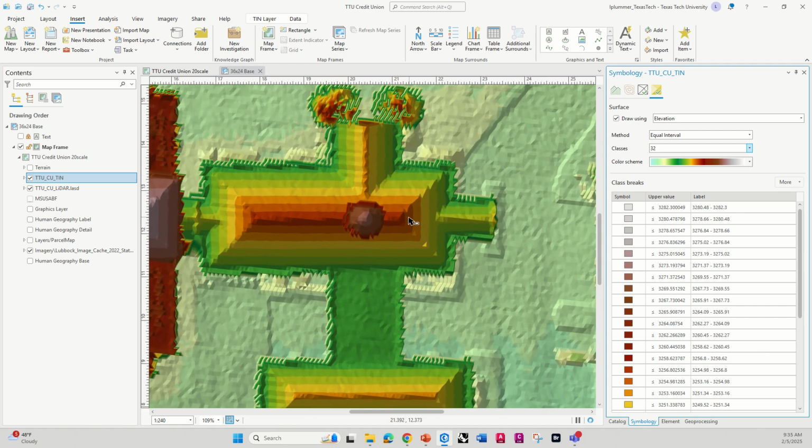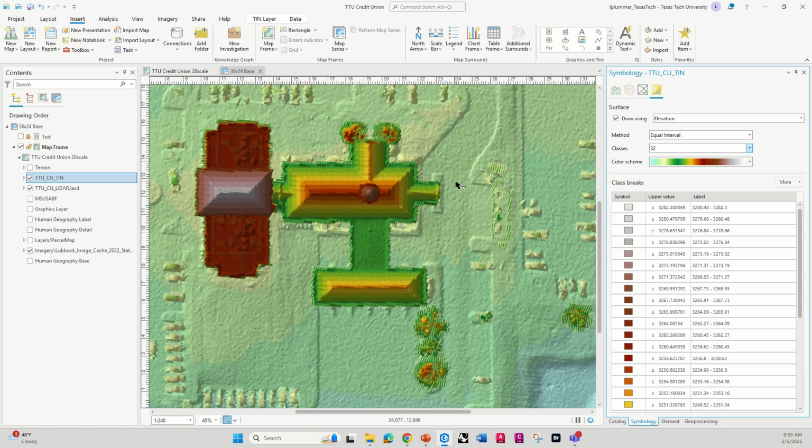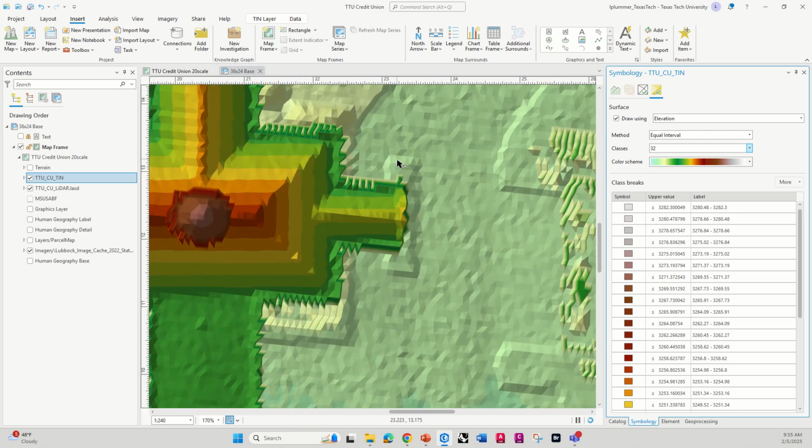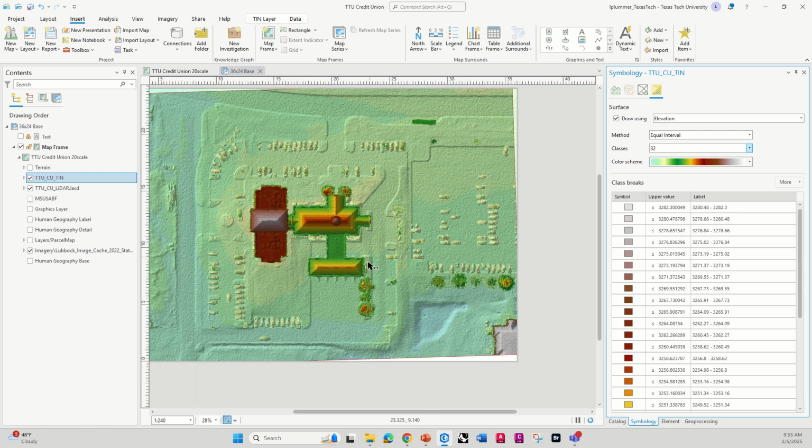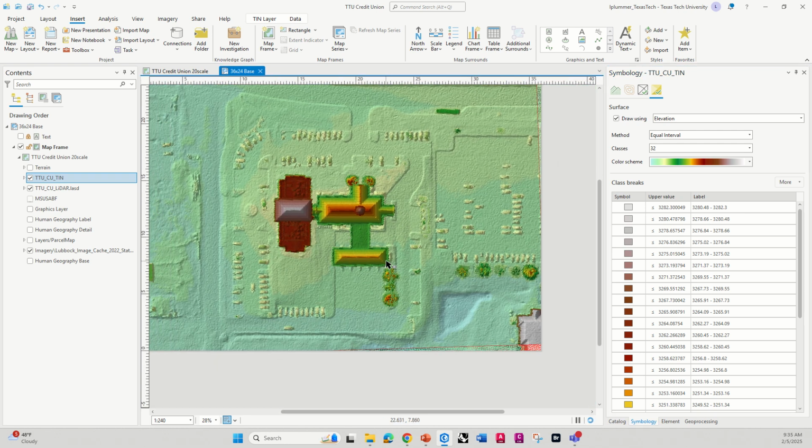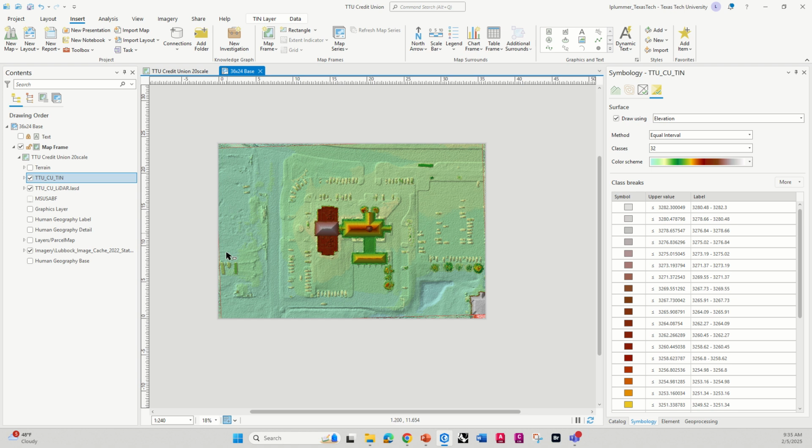Will was showing me, you can even see the height of the roof as it descends down. Okay, you can see that garden bed around the drive-through, and you can see, most importantly, the general lay of the land as to how the civil engineers graded it. And you can see that nearly all the water is coming down, not all of it, but at least on this half of the site is coming down to this point here.